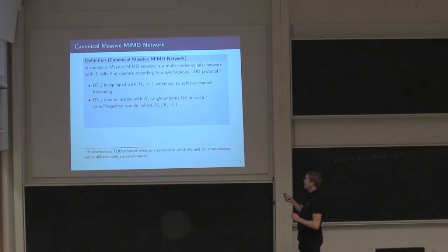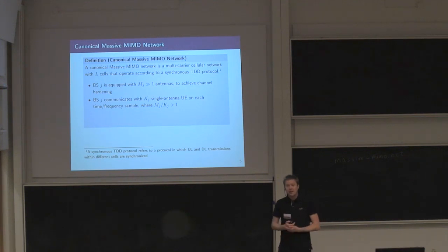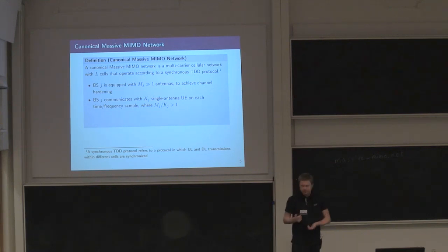They are single antenna users, and they are all sharing the same time and frequency resources. And we typically have more antennas than users. Exactly how many more antennas depends a lot on how you would like to design the system. And we will look briefly at that later on as well.